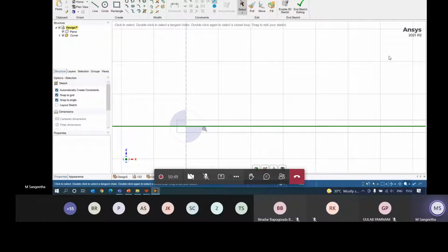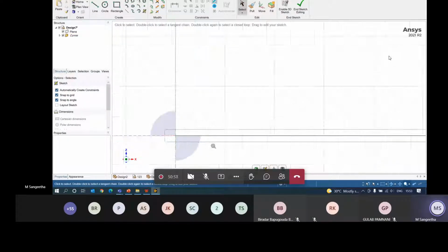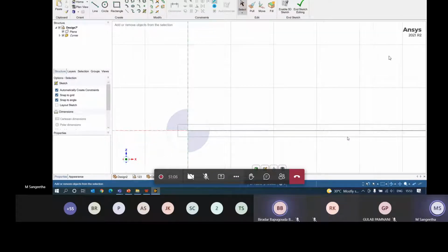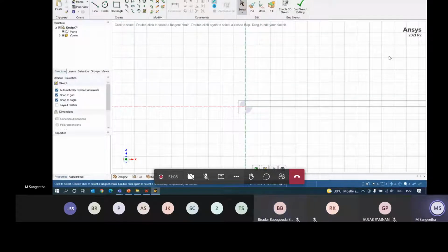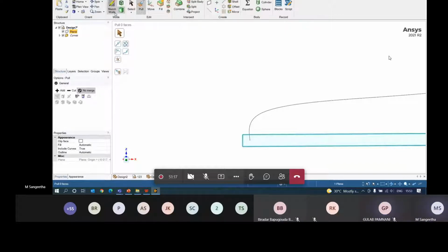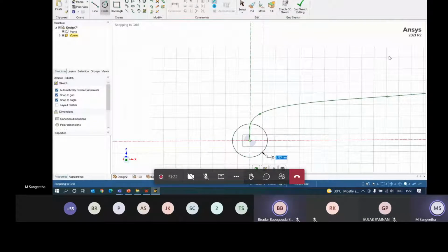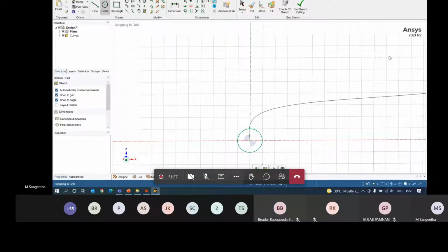See, there is a shading available here, which you can use as a start point of yours. So this is going to be the center of your geometry. That reference is here. Okay, so I'll just zoom out. So you can see here, this is the center point. Select, and I'll go back to sketch mode. Okay, and then go back to solid mode.